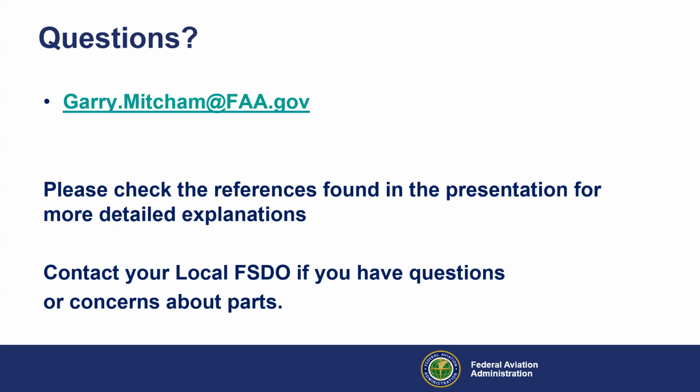Okay, on the same line of thought, one of the things easily obtainable online is parts from salvage aircraft. What does someone need to look out for when getting a part off a salvaged aircraft that they're buying online? On salvage aircraft parts or just used parts, you want to make sure the part is approved for return to service by somebody listed in 43.7 who's authorized to approve for return to service.